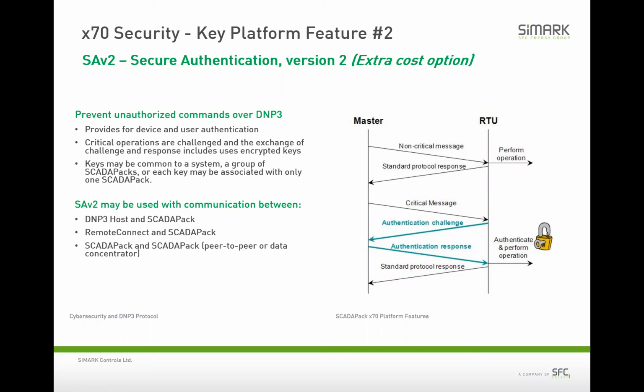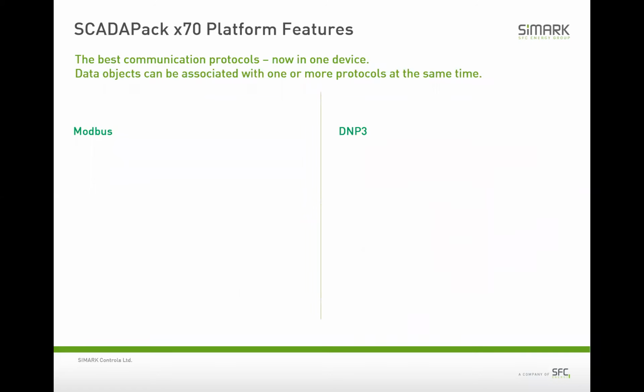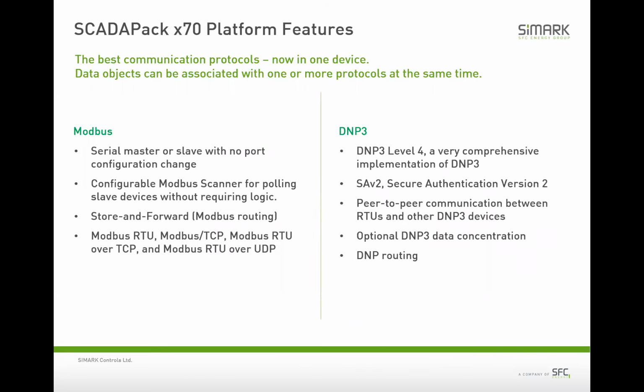Recently this year, we added a new version of firmware in all of the SCADAPacks as well. Schneider's added in, initially out of the box, the RTU needs to be configured so that it will challenge the user for a password or not before you can get into the RTU. So that's separate from secure authentication. SAv2 provides a much more comprehensive way of controlling access to RTUs by users and devices. So what we've done with the X70 is combine two main platform features in the Modbus and DNP areas together into the same single RTU.